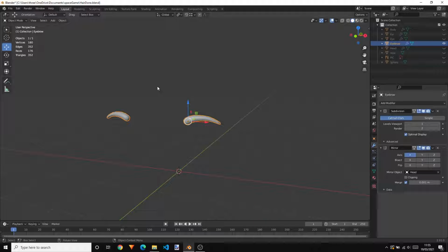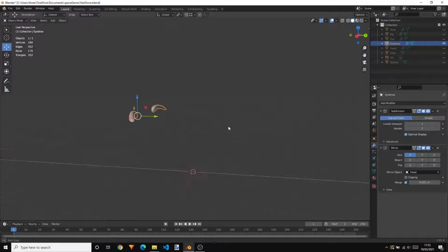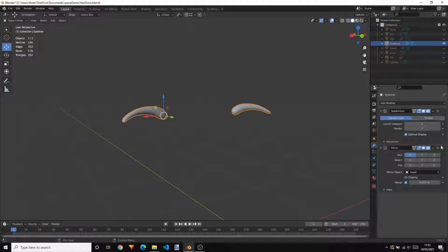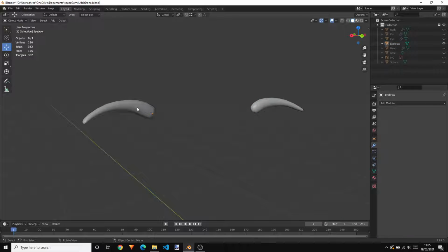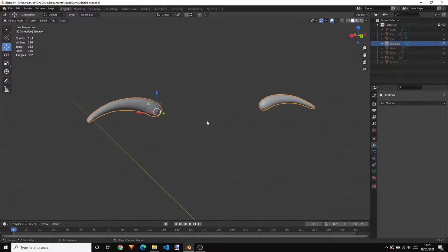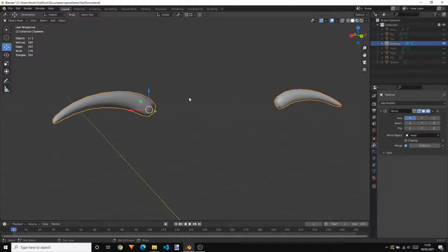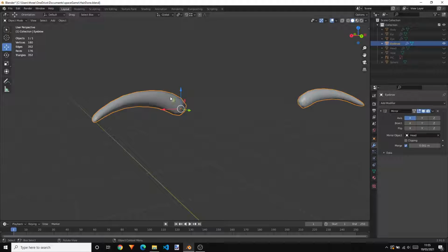Make sure you've got that project saved, because now I'm going to start applying stuff. I'm going to start applying these modifiers. So I'm going to apply that, and I'm going to apply that, and now we've actually got, no, I'm not going to apply the mirror modifier. And that's because when we do the UVs, I want them to share. Probably, I don't want to have to paint it twice.